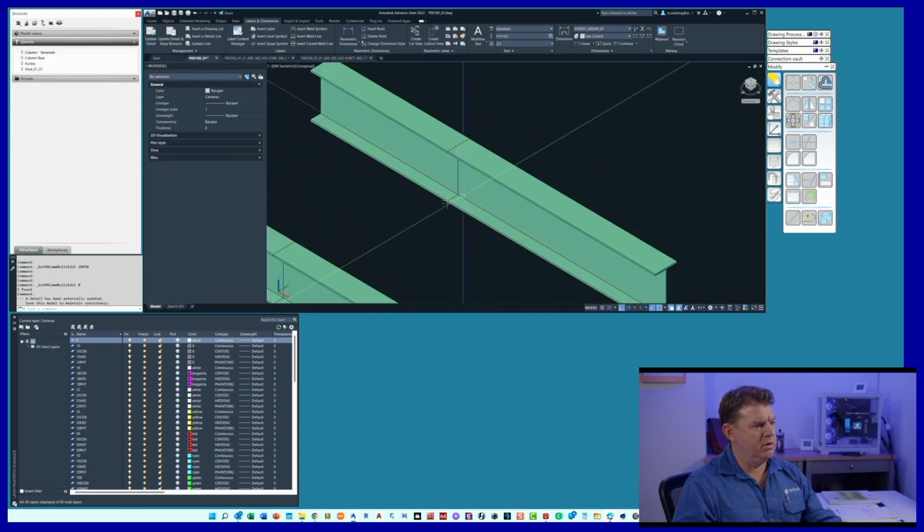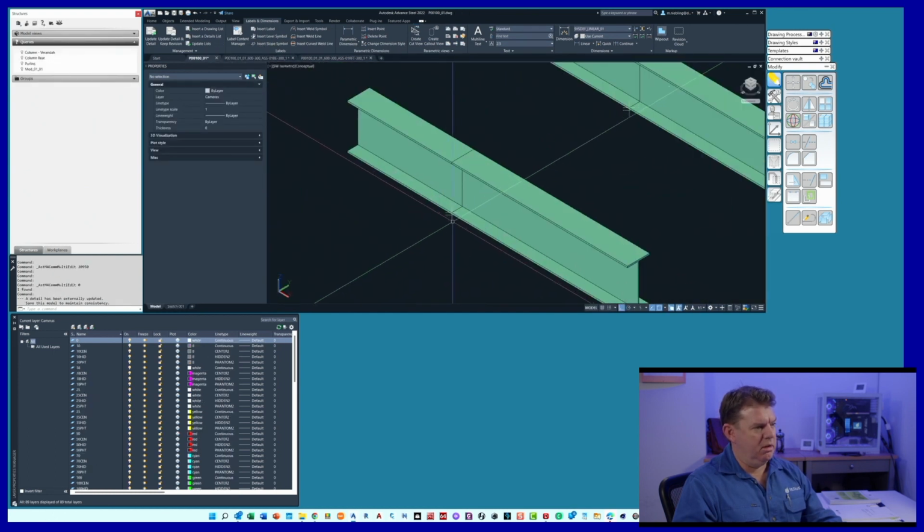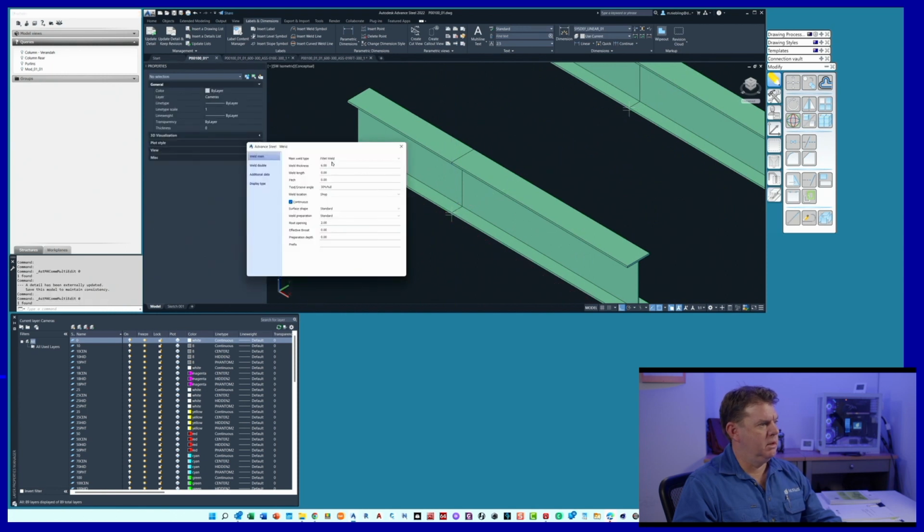Let's go back here, let's try this other weld here. We've got a backing bar here, let's put that in there. So what we do with backing bars is if we use a weld thickness of 1, that will allow a value not to show up, because 1 is our default weld that doesn't show up. We won't put it there. We'll put a groove angle in there.